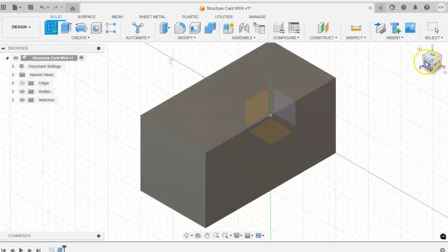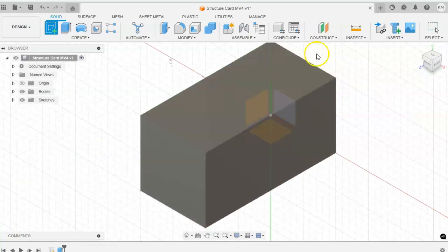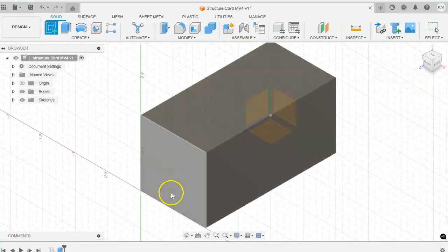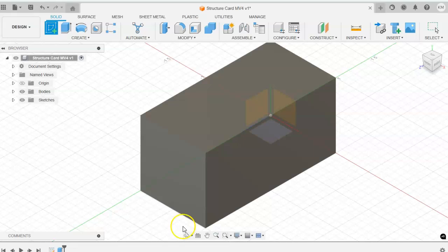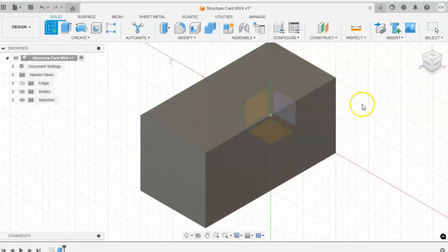And I'm going to choose, this is where we can choose a surface of our object, or we can move over to one of the original planes from our origin. I don't know if you can see that there in the background, kind of behind our rectangular prism. But we're going to want to sketch on the XY plane again. I want to get back on this surface here. And I could spin around and sketch on the back of the surface just like I did on the previous drawing. That would be absolutely acceptable.